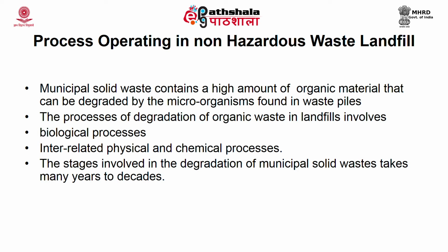Now, this biodegradable material will follow a biological conversion route. In addition to the biological route, there will also be some physical and chemical reactions which take place. Similar to hazardous waste, there are physical reactions: after biodegradation, the volume of waste gets reduced. So, there will be compaction, depression and all those things. Simple alteration in the physical property of waste will be there. That is a physical process that takes place inside the non-hazardous landfill.